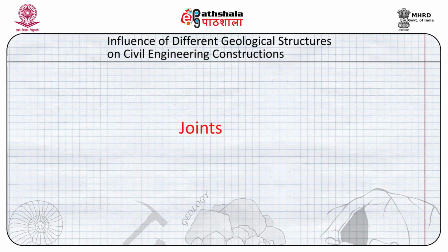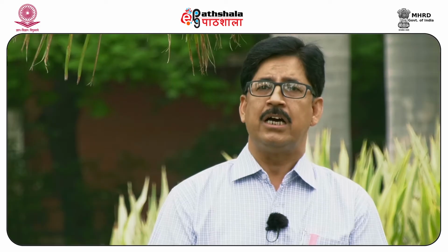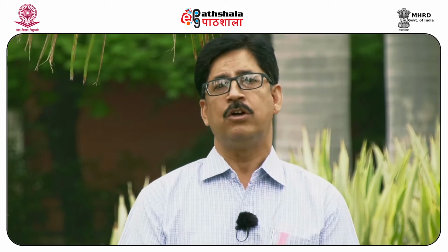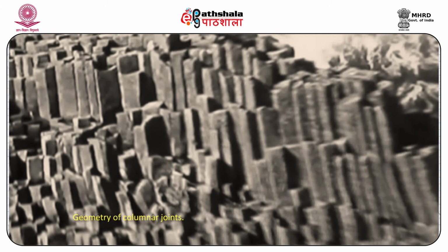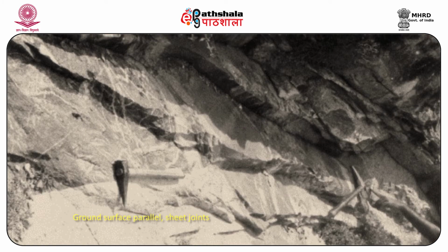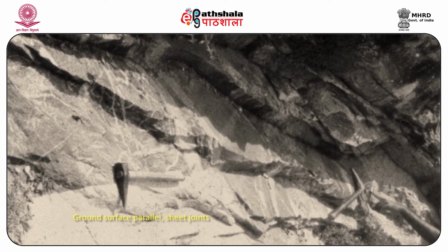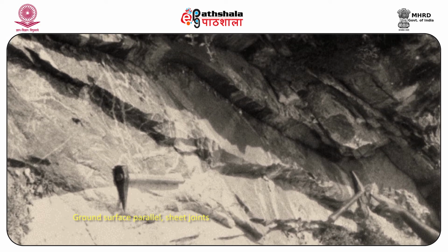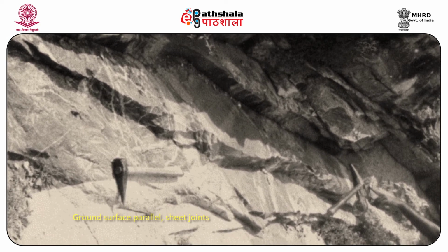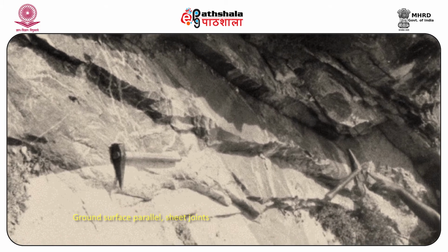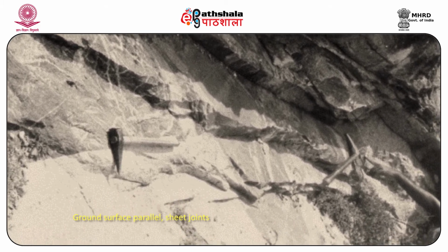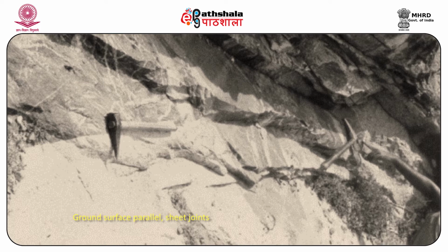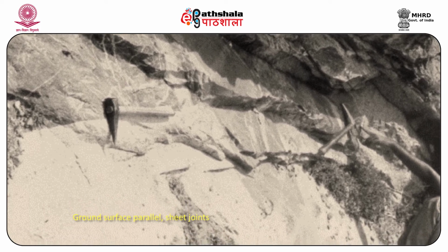The joints separate a rock mass into different kinds of blocks, and these block sizes and shapes play a very important and major role when we load the rocks by founding some structures, or when we unload the rocks by large scale excavations.